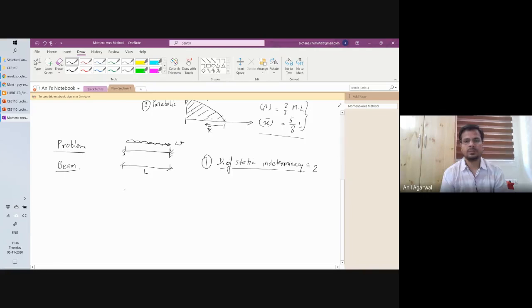Or alternatively, you can think of it, instead of a simply supported beam, you can say it was a cantilever. If it was a cantilever, it was allowed to move down and it was allowed to rotate here or move up, just keeping the sign convention positive. So now both of them are restrained at this end. So these two. Okay. And this movement was anyway disregarded when we considered it a beam. If we had called it a frame, then that movement would have been causing another degree of static indeterminacy. But in this case, we have only 2 because we are disregarding the axial deformations.